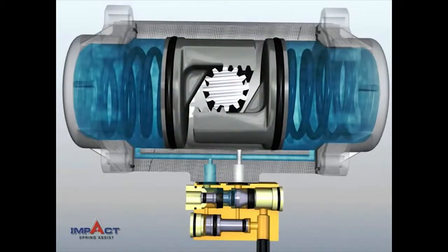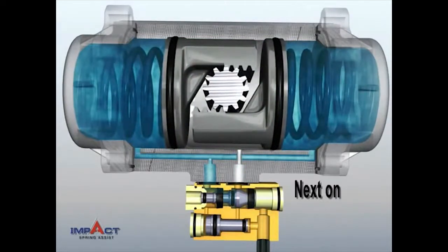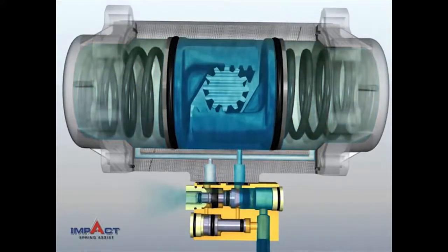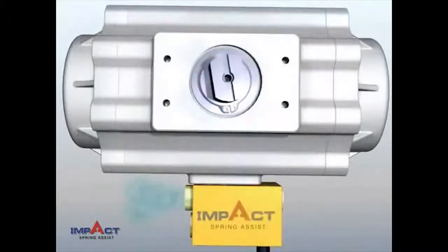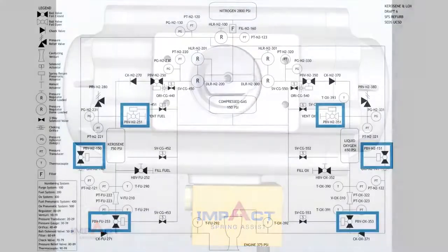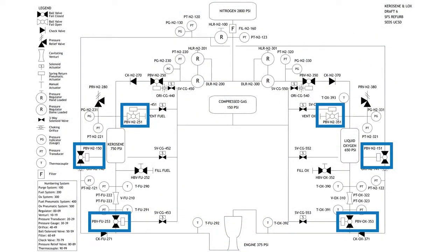So it gets the on command, air will flow into the middle, and it'll push those springs out to the sides, and it'll turn that cog 90 degrees for you. And then you give it the off command, and it'll take air out, and that pressure differential will let you close this. This is a little bit different because it lets air in both ways, but this is just a special one, so don't worry about that. That's not how ours works.